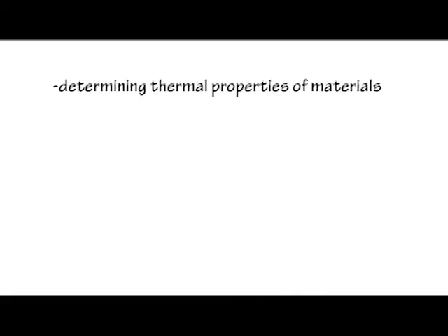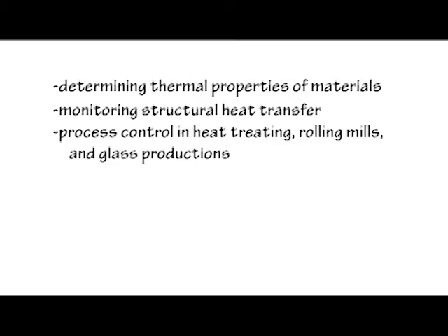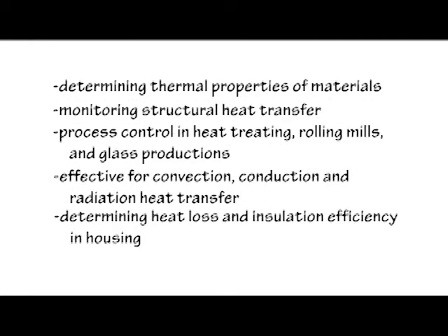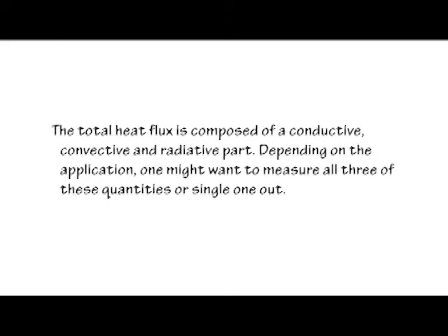These are the applications of heat flux sensors: determining thermal properties of materials, monitoring structural heat transfer, process control and heat treating in rolling mills and glass production, effective for convection, conduction, and radiation heat transfers, determining heat loss and insulation efficiency in housing, and analyzing aerodynamic wind tunnels. The total heat flux is composed of a conductive, convective, and radiative part. Depending on the application, one might want to measure all three of these quantities or single one out.